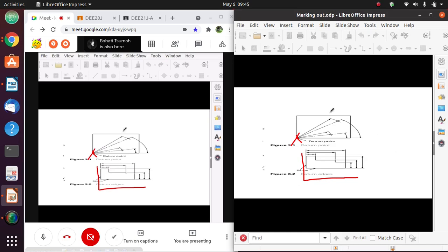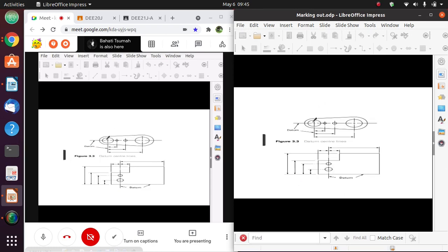For us to make a drawing, a sketch, or anything on a workpiece, we have to have a point from which, when we use a tool like a scriber or a divider, we can make the measurements. So it can be an edge, it can be a point, it can also be a center line. When you talk about circles, spaces that are circular in nature, holes that are circular in nature, since you cannot specifically measure